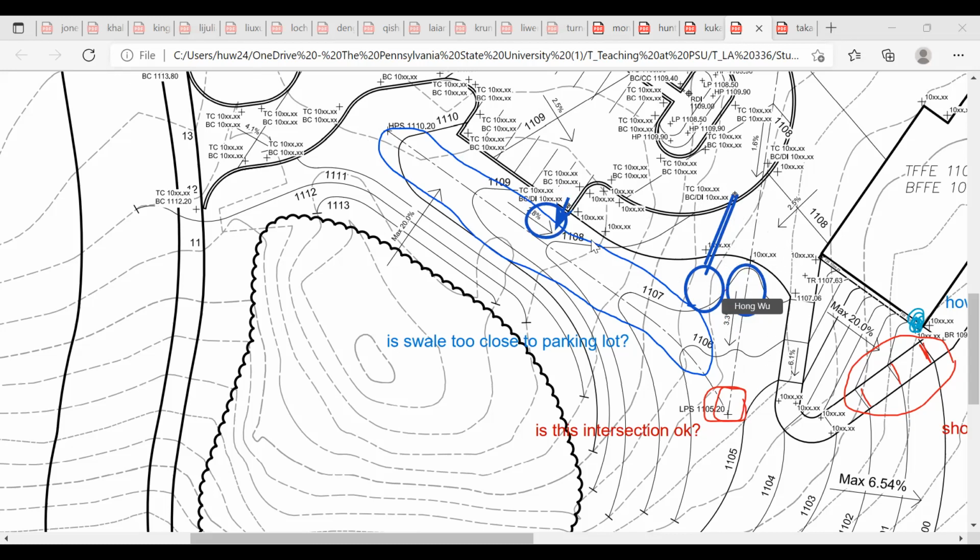And these should be away from the divergence swale because you don't want to mix up the water. That's basically how you represent it. And remember that when you design a trench drain here, no water enters from the BC, but the bottom of the trench drain is 0.5 foot below that BC. Okay, and then you calculate a 1.5 or 2% slope at the bottom of the trench drain. So you know the elevation here where water enters the cell.